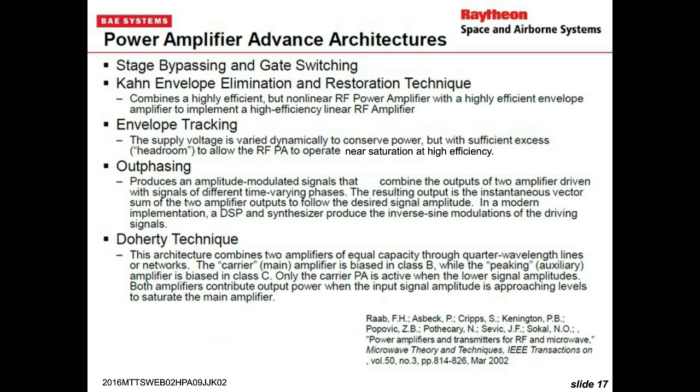Outphasing basically uses signals of time-varying phases to efficiently combine at the output as an instantaneous vector sum to allow the desired signal amplitude. And this has recently received a lot of attention in the literature. Doherty, you've seen this as a mainstay in publications, both in LDMOS and in GaN.